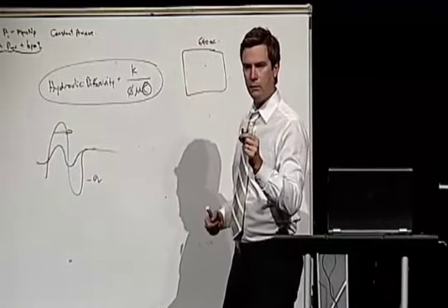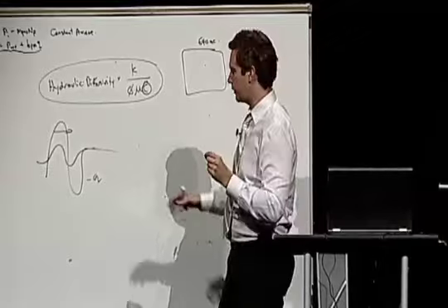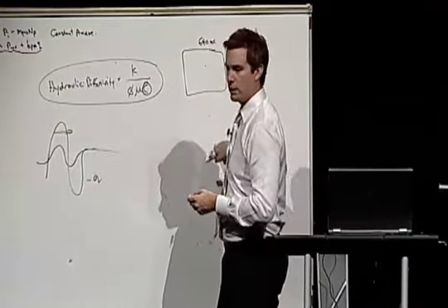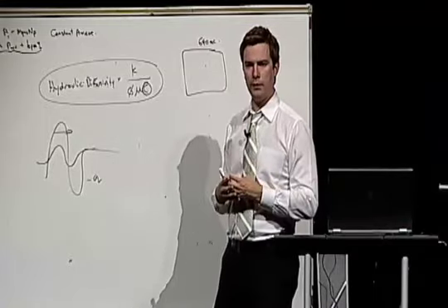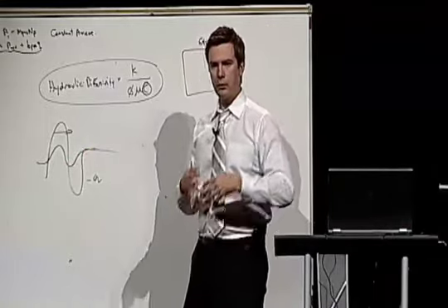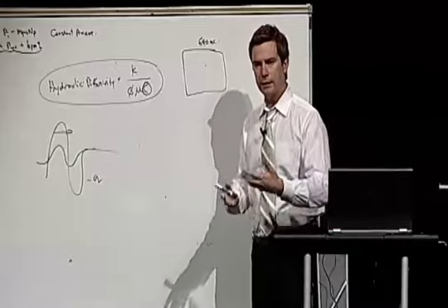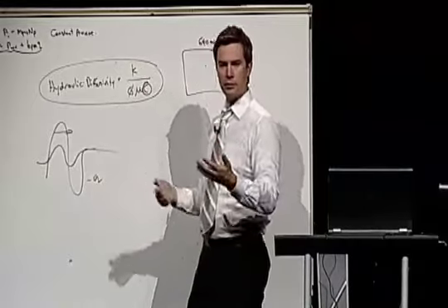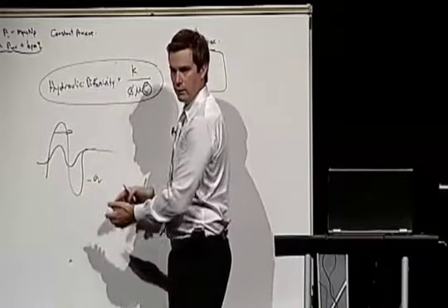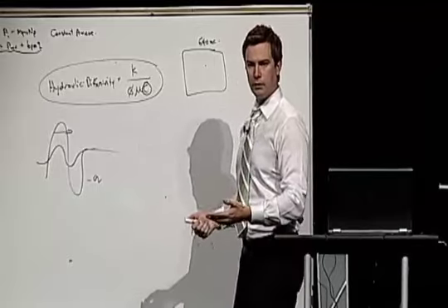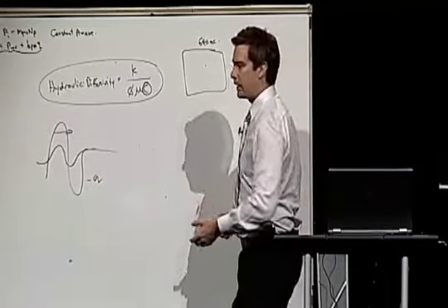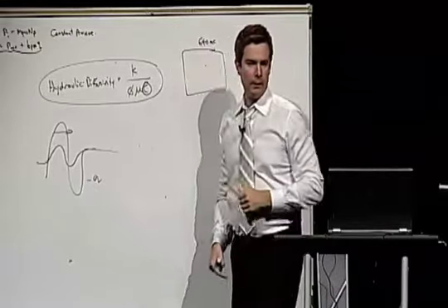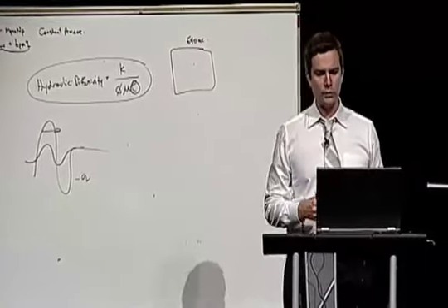If the flow rate's too small, in theory, this flow rate could be 1 drop of oil per day, and we'd still be able to get the pressure transient to move through the reservoir. But we wouldn't be able to measure anything because the amplitude's not big enough. So if we want to have a pressure transient that we can actually read and get some information out of, we need to have enough of a production rate there that we can actually read it. So the amplitude of that signal is analogous to the production rate, and the hydraulic diffusivity is analogous to the speed of the pressure transient through the reservoir. And that's really how we describe the radius or region of investigation.